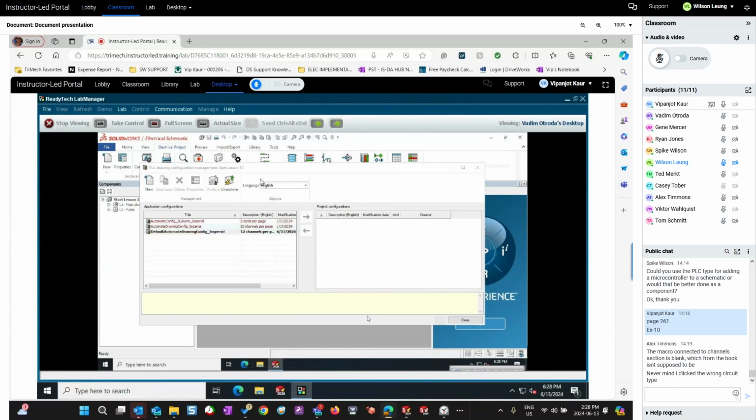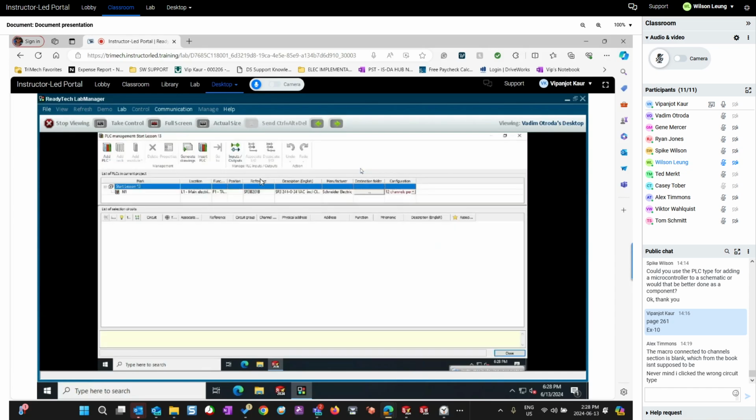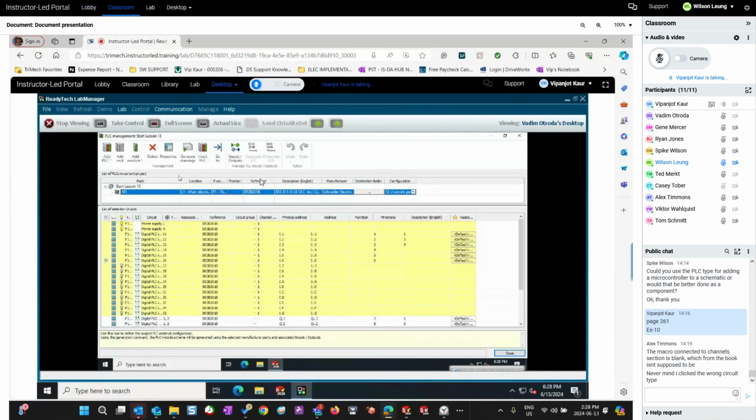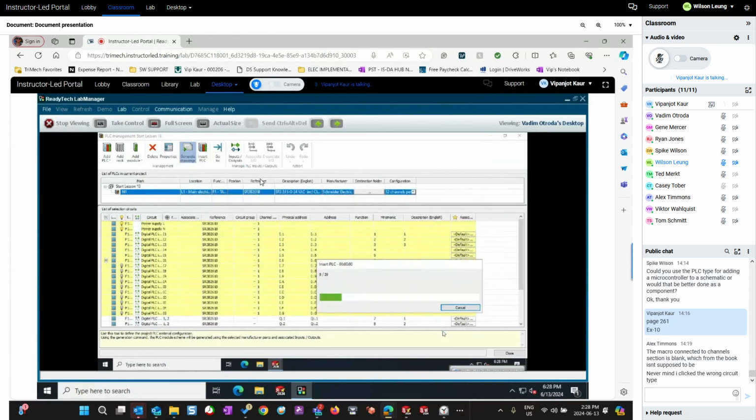Close this window. Now click on PLC Manager button, right on the big PLC button on the Project tab. PLCs. Now let's click on the PLC, generate a PLC drawing. Click the generate drawings button. Amazing. Click OK on the bottom, generate it. And let's check your result.